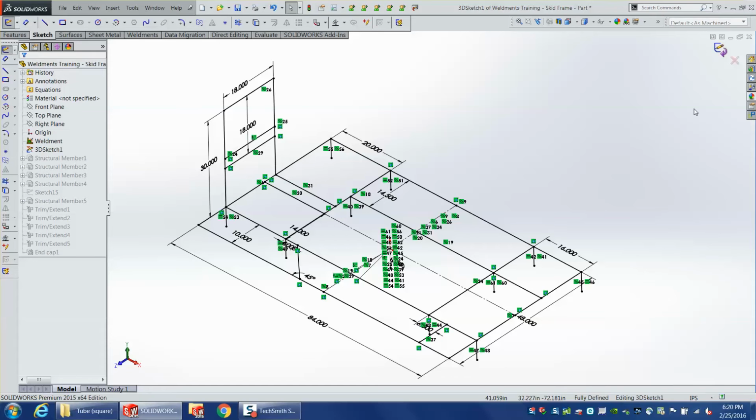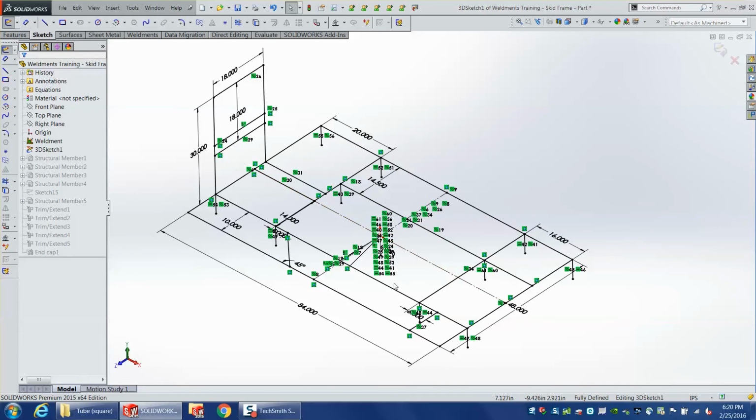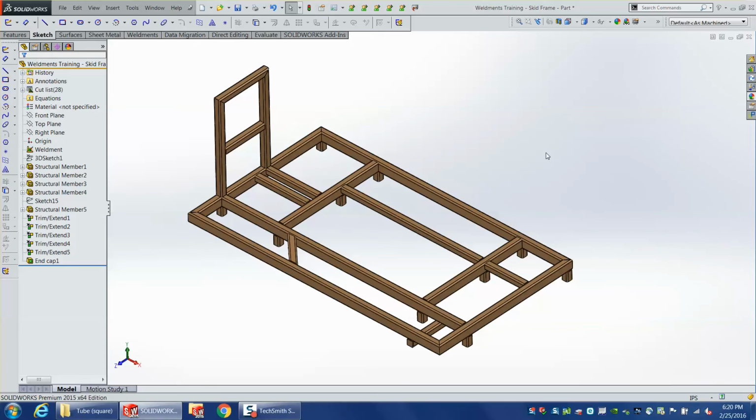Right. So he's asking, what's the advantage of a single part weldment versus a sketch-driven assembly where everything is parametrically linked anyways? And there is some flexibility that you gain there, but there's also functionality that you lose. You lose some of your cut features and those kinds of things, but the most important thing is having it all in one file. But you can, with driven sketches, when you drive the whole assembly with just sketches, you can have it in a file. Are you talking about an assembly file with multiple parts referenced by that assembly? Yeah, like a sketch driven the entire design.